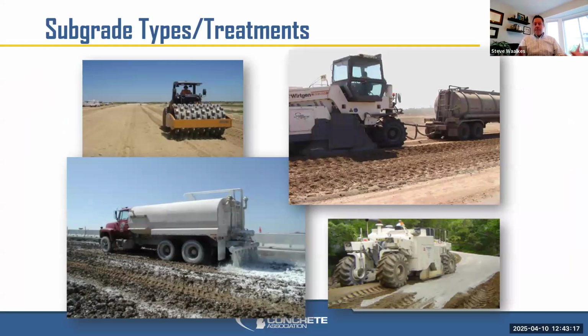Okay, now let's get into building the thing out of concrete. There are options for subgrade treatments. We don't see a ton of this in Michigan. We're seeing some agencies or owner types use it for certain areas where we have some poor soils. As far as chemical stabilization of the clay or silty soil, whether using lime, fly ash, or cement, there are options to stabilize those soils.